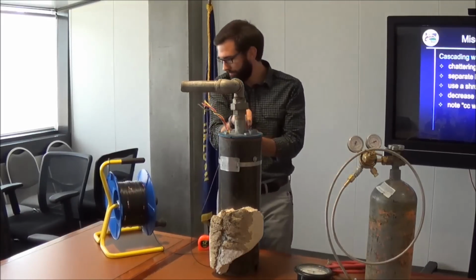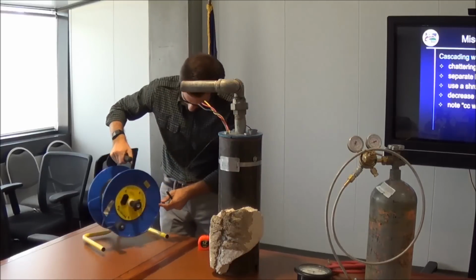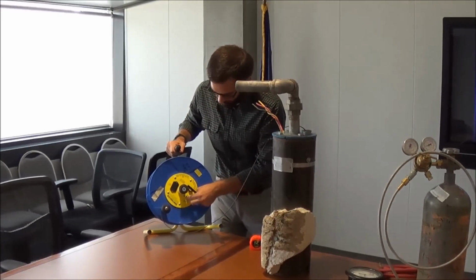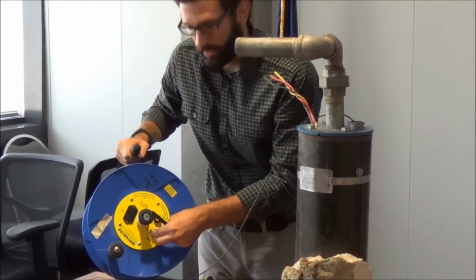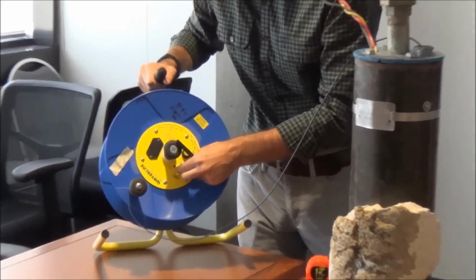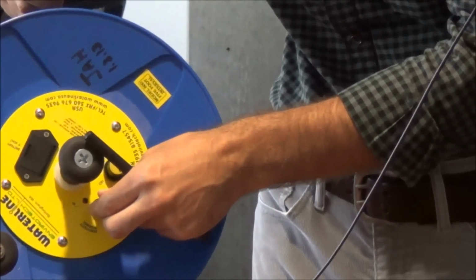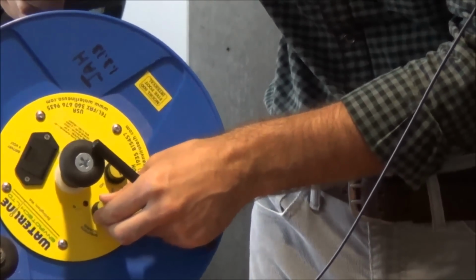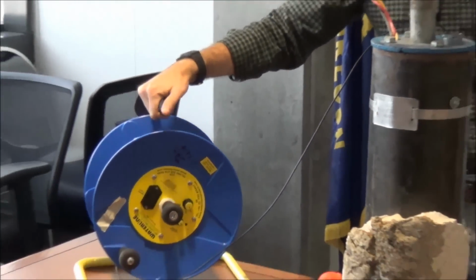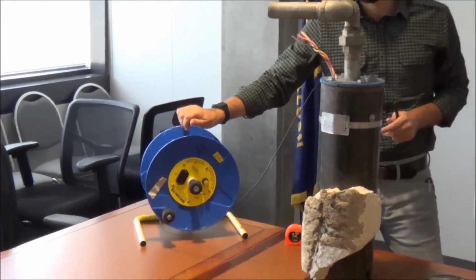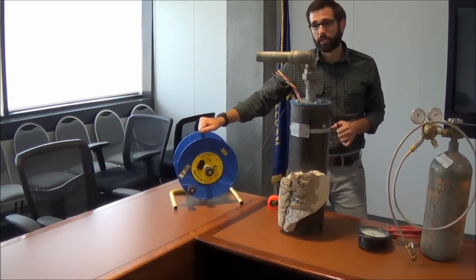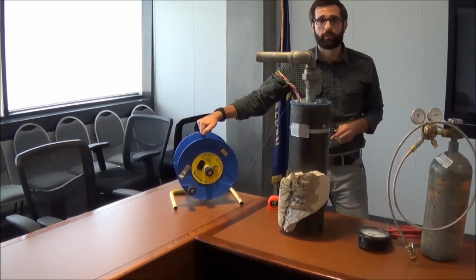Another thing you can do is on here, there's a sensitivity meter, which is how sensitive this is to the electrical conduction. If you turn that down, that tends to reduce a lot of the chattering, and that helps. I find that helps a lot. And then, if you're still having problems and you just can't get it without the chattering, just note that in the water level. That's beneficial to us to know that there were issues while you were out there.